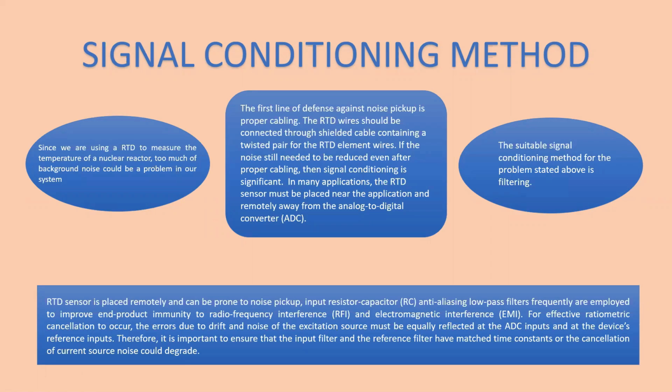I am Kavin and I am going to present about the suitable signal conditioning method to solve the problem in a nuclear reactor, to measure the temperature of the nuclear reactor. So the first signal conditioning method will be filtering. Since we are using a RTD to measure the temperature of a nuclear reactor, too much of background noise could be a problem in our system.